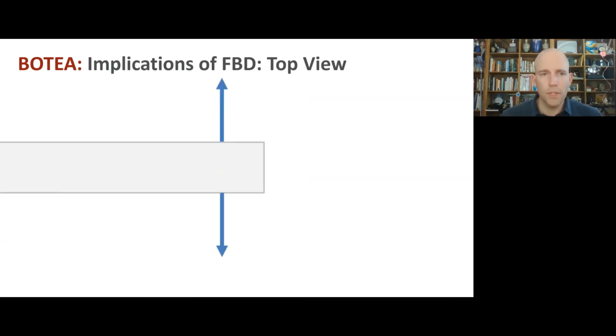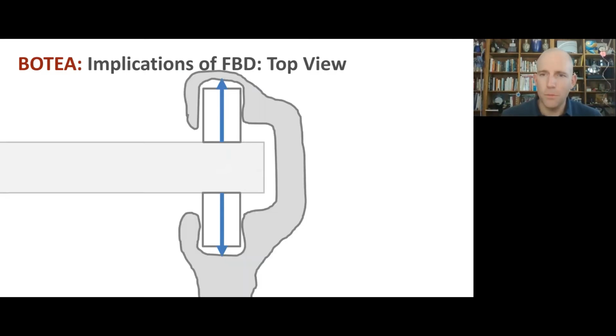How about from the top view? If we look at this thing from above, these are the normal force arrows. We're looking endwise on the rope or the payload force. Let's think about what we can learn about our system from that view. Well, this free body diagram is in static equilibrium as long as those forces are collinear. Everything is coplanar. Maybe we get some wheels there. Maybe those wheels are going to be connected by some structure. Well, now we can start to see some things that we care about for our structure.